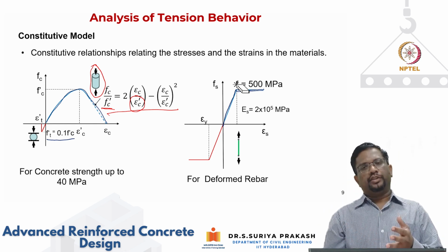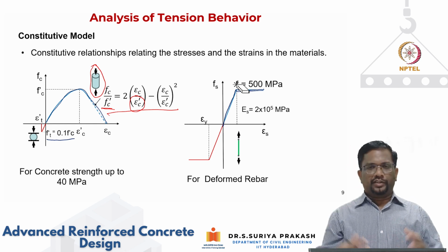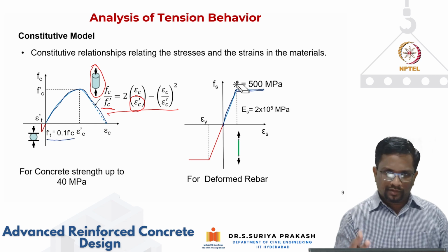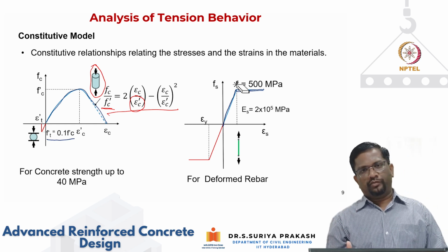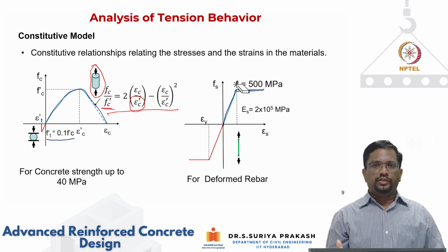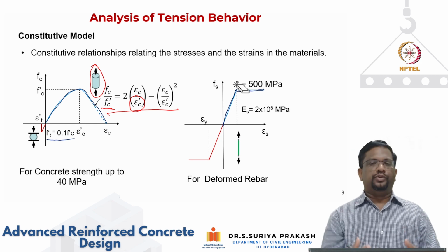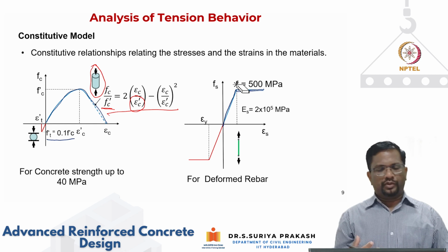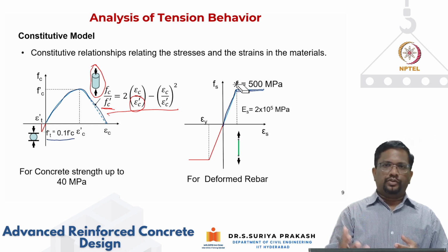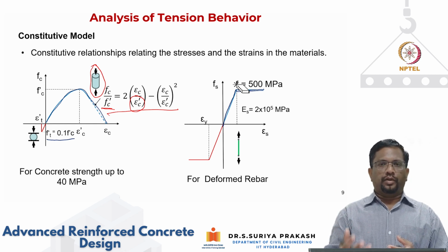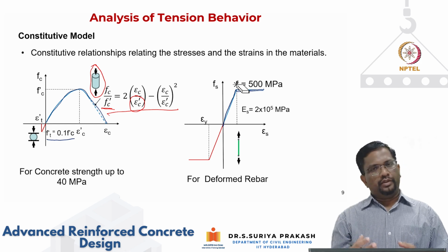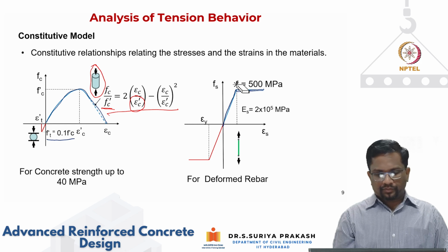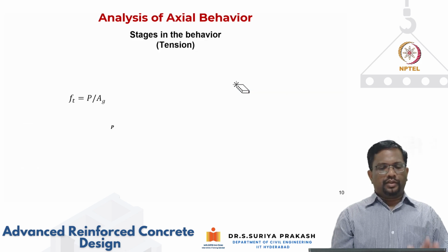It has to always satisfy equilibrium. In this case, we are talking about axial force equilibrium. Then it has to satisfy strain compatibility, or compatibility of deformations. And the third one is that we also need to follow some constitutive relationship of the material. Here we are dealing with reinforced concrete, so concrete should follow some constitutive relationship in compression and tension. Similarly, for steel also we need to follow some stress-strain relationship in compression and tension. So this is your constitutive model.